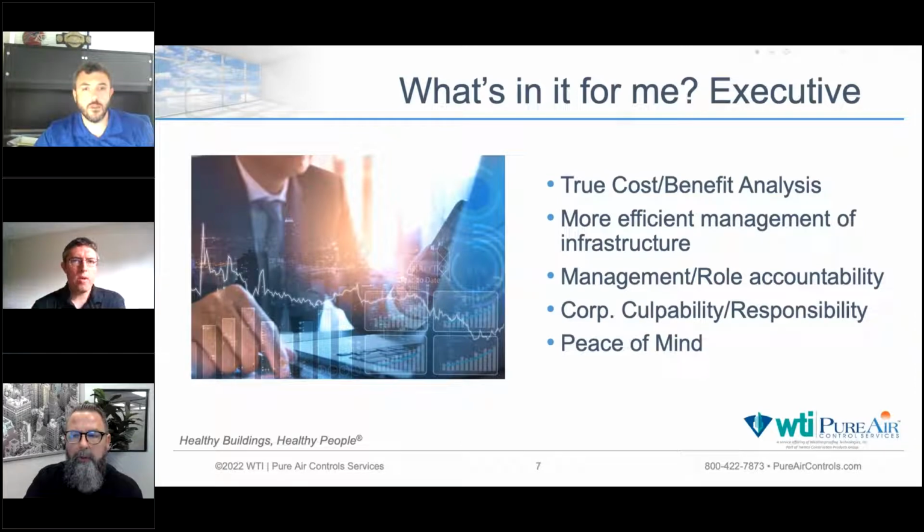Great point, Frank. One thing to add to that too, I know I keep hitting these VAVs, but one of the indirect results that came out of our assessment recently is, hey, you have similar make and model VAVs serving other critical areas. What happens when they start to degrade? So now that executive team has an idea, hey, we should start planning for this. We should start identifying these other areas that are critical. We should start thinking about reviewing the plans, seeing how many VAVs we have, and making a plan for going through these, because functionally they're fine. It's just an age and hygiene thing.